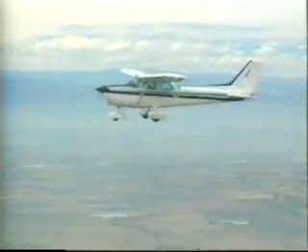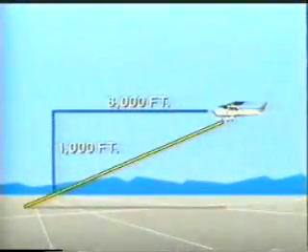While this information is important to airplane manufacturers for determining performance criteria, it's also very significant for pilots, since the LD max provides for the best power-off glide ratio. This ratio represents the amount of horizontal distance traveled for a specific amount of altitude lost. For instance, let's assume this airplane has a glide ratio of 8:1, meaning that it can produce 8 pounds of lift for every pound of drag. At this ratio, for every 8,000 feet you travel horizontally, you will lose 1,000 feet of altitude.